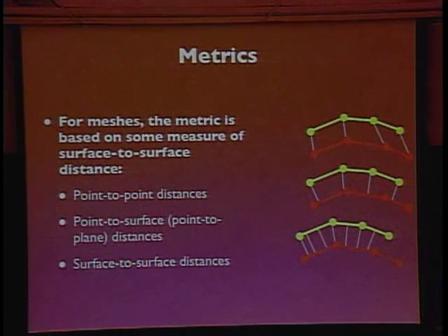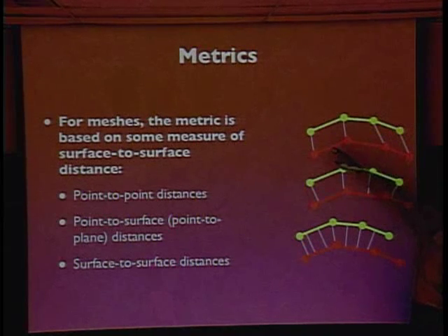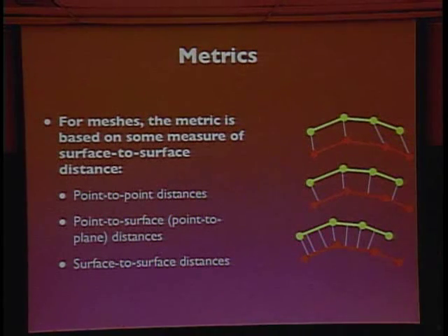So in particular, what you can do is have each point on your moving mesh, or each point on your fixed mesh, it doesn't really matter that much, and have each one of them tally their vote or contribute their opinion to some degree about how well that particular local location of the mesh seems to align with the other mesh. So what you can do is, if the green one is the moving mesh and the red one is the fixed one, kind of doesn't matter which one is which, but what you can do is basically take the moving mesh, take each point, and calculate its distance to the closest point on the fixed mesh. So that's going to be some distance.